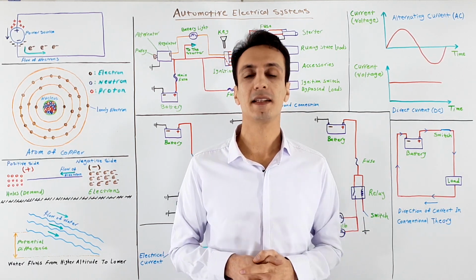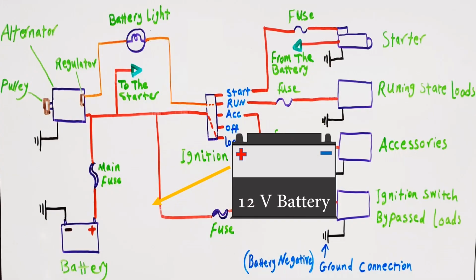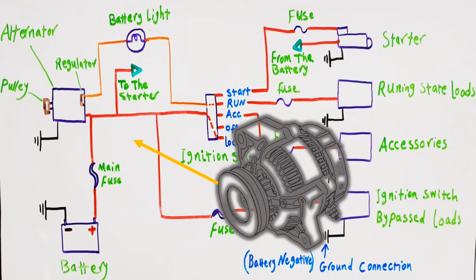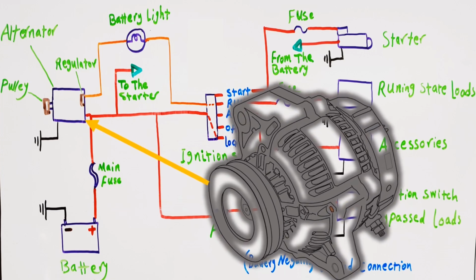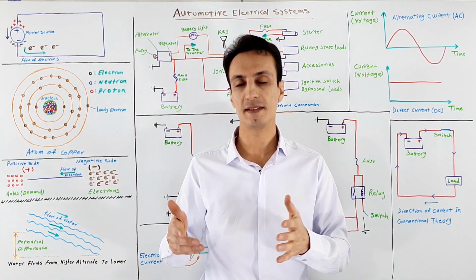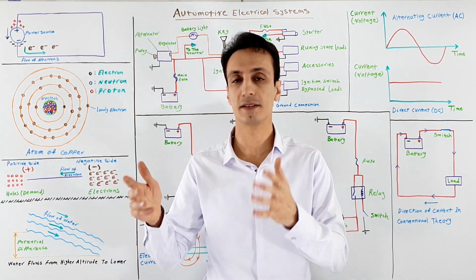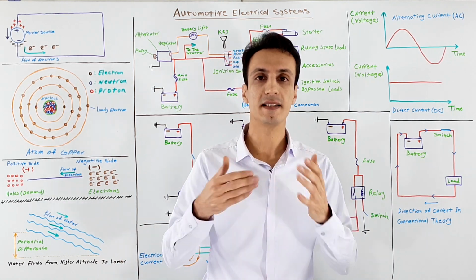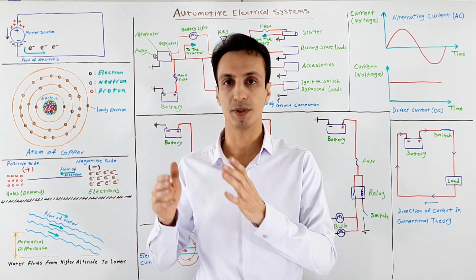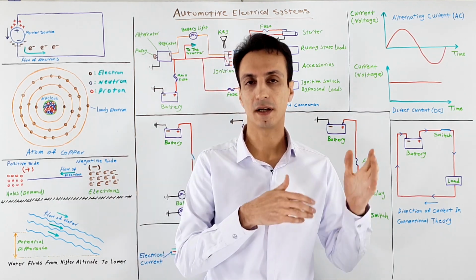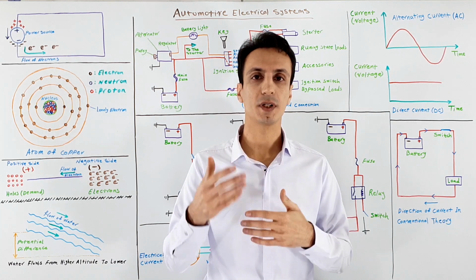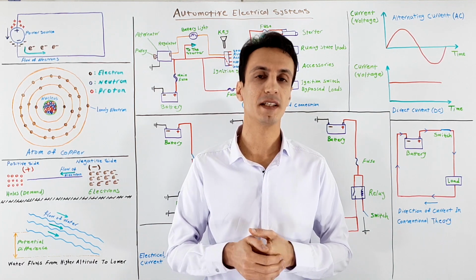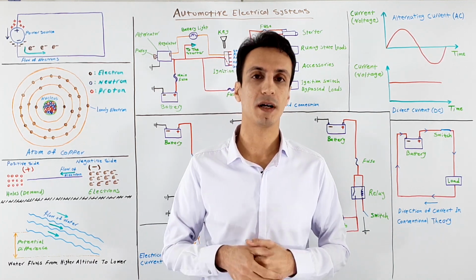Three main reasons can cause this problem. First, maybe the battery needs your attention, or probably it's dying. Second, maybe the alternator doesn't work properly, or its drive belt is loose. And third, maybe there's a parasitic drain from one of the electrical systems or accessories of the car that is drawing current from the battery with an amp rating that is less than the rating of the fuse protecting that circuit. Diagnosing all three requires experience with digital multimeters and test lights, but for the third one, I have a simple solution that owners can do, and sometimes it works.